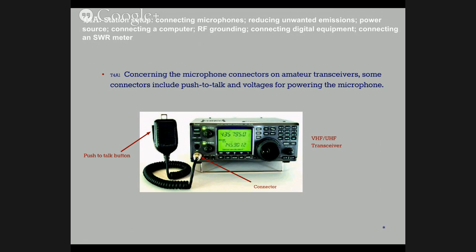I have one right here. Not sure what I did with it. Should probably find it. Here it is. It's got a multitude of buttons on it. So it uses one line for signaling. And it is just an RJ45 connector, but this microphone has a different pinout than, say, my, this is an ICOM. It has a different pinout than my Yaesu transceiver, and so this would not work with it in most likelihood.